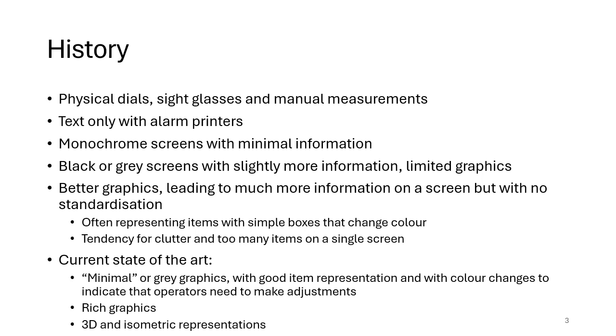That can also include multiple levels of display. So you might start off with a high level, and then you would drill down through various levels until you get to the level of detail that's important. So at a very high level, you might just have a whole graphic of the plant, and then there might be simple messages for each plant area, and then you click on those areas or tap on those areas, or maybe you're using pinch and zoom or swiping gestures, but you can then drill down until you get to the level of information that's appropriate for the actions you need to take.